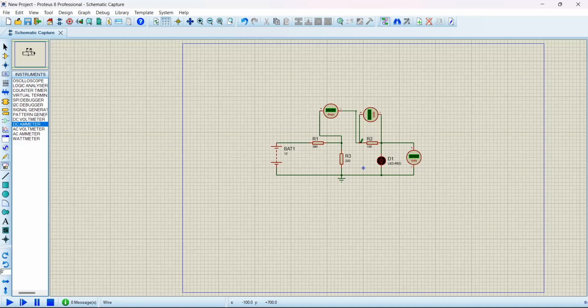If you want to know the current, you need to open the circuit and then connect your ammeter to complete that circuit. So now I use this ammeter to complete the circuit because I've removed that wire, and now it's working as the wire I've just removed. Now it's completing the circuit as that wire was completing the circuit before. Therefore, I'll need to run my circuit.